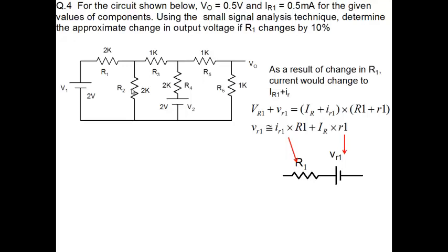Where instead of changing some voltage or current in the circuit, I change the value of the component itself. And what we are saying is you can do that analysis using the small signal approach again. Same thing is valid here. Note that you've already analyzed this particular circuit, and we are changing the value of R1 by a certain amount. So let's focus on this particular resistor. The voltage across it is VR1 initially, the current is IR, and the resistor value is R1. Now we change R1 by a small amount, shown over here as ΔR1.